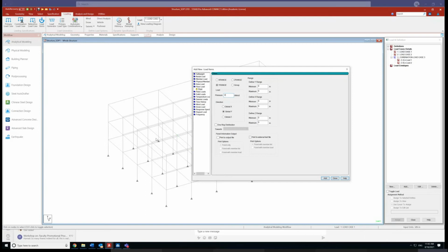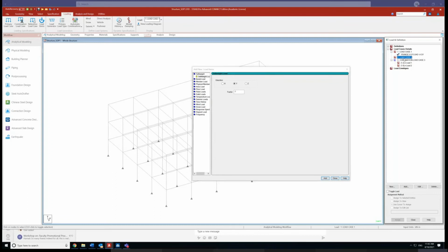It will apply everything here in this one to all the floors, and it will apply them as two-way slabs. If you want to specify a one-way slab, then you have to specify that here, one-way slab, and in what direction you have to say that this is one-way slab. Just for simplicity, I will add it like a load pressure all over. Then I'll go to load case number 2, which is also a live load. Live load, I will add it also as a floor load, which is equal to -2, for example, kilonewton per meter square. Also apply it everywhere.